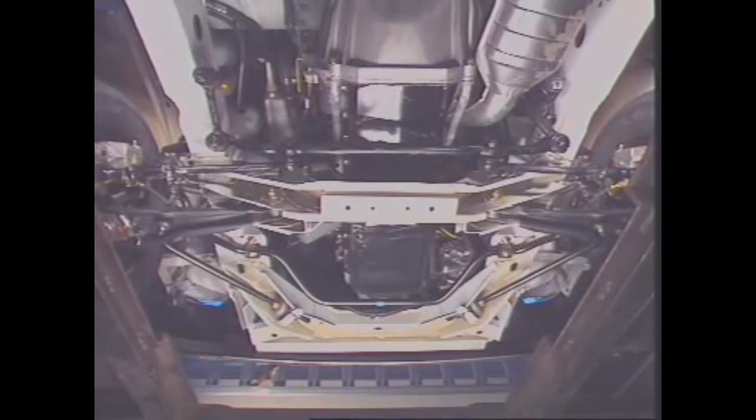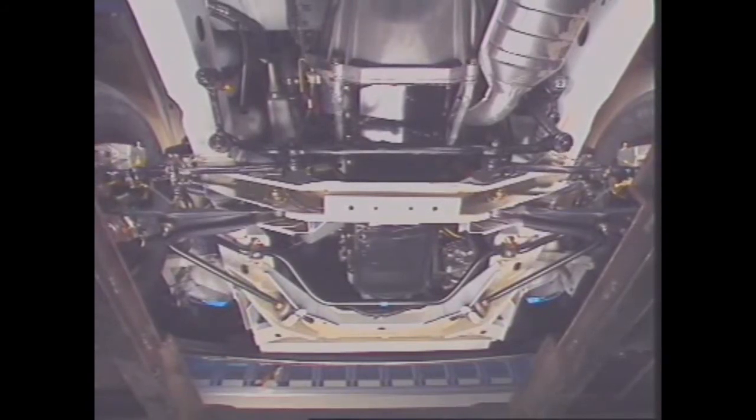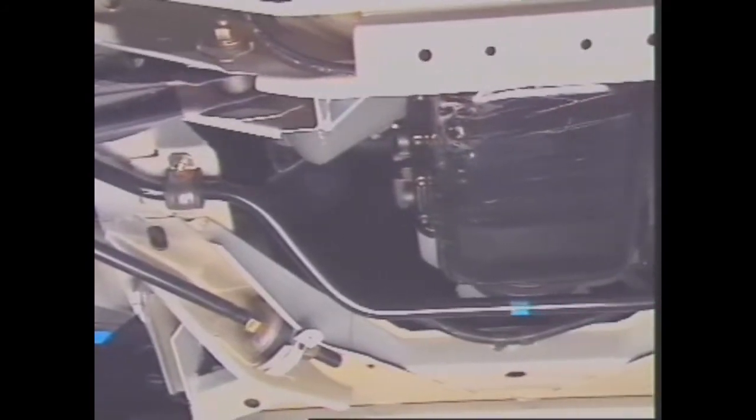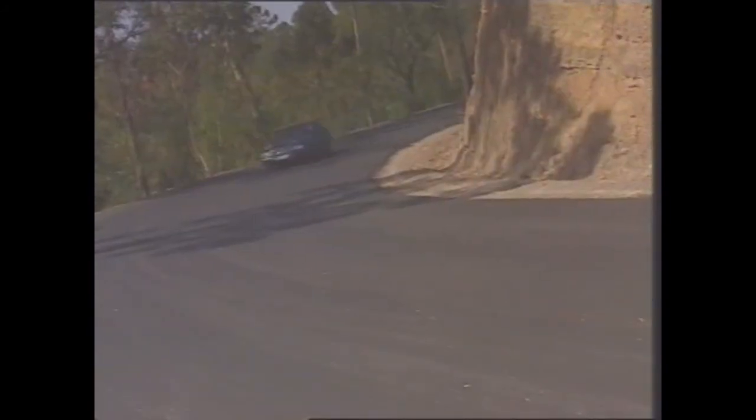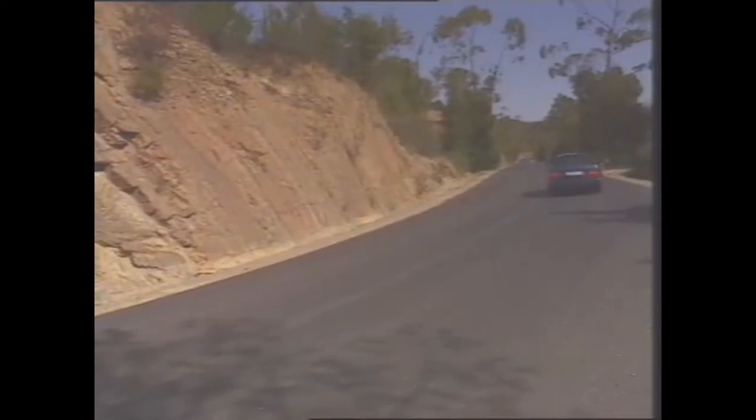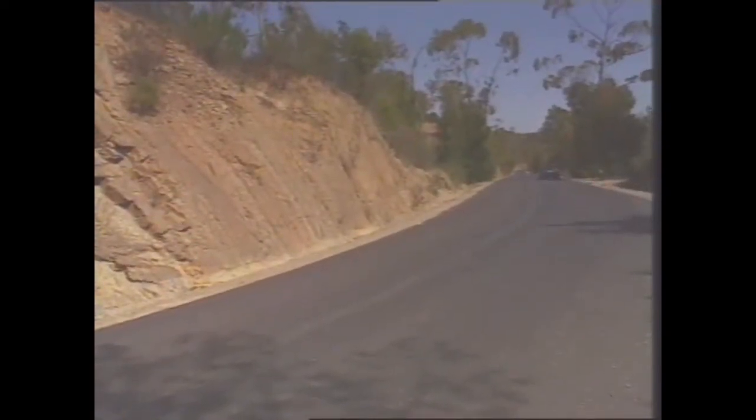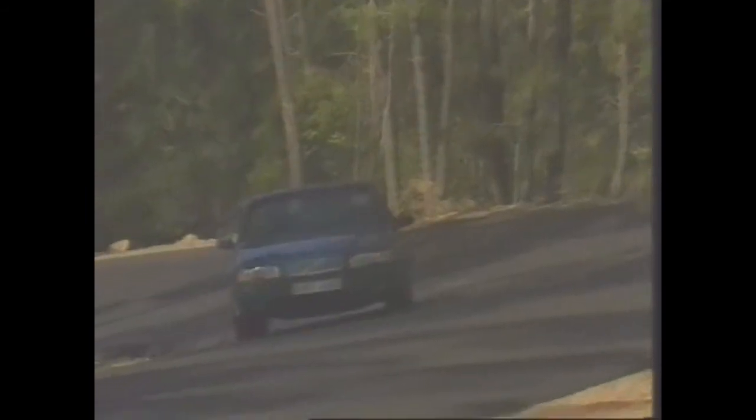It is used in light vehicles as a stabilizer or anti-roll bar, connected between each side of the suspension on the front and sometimes the rear. When the vehicle is turning, centrifugal force acts on the body and tends to make it lean outwards. The anti-roll bar or stabilizer tries to use its connections to each side of the suspension to resist this roll tendency.